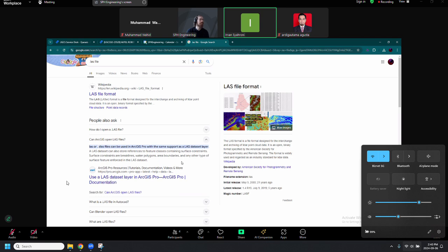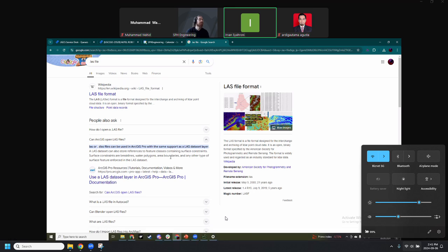So you just said to me that we should try to process the point cloud to become a model, so that's why it becomes TIFF, right? Yeah, okay, I get it. Thank you. Well, you can always generate a GeoTIFF file from the point cloud, but UGCS on its own doesn't import point clouds, because at this point we don't think that we need to, because with the amount of data a point cloud usually has, visualizing all of it will take a large toll on the hardware. So we use these formats just for efficiency.